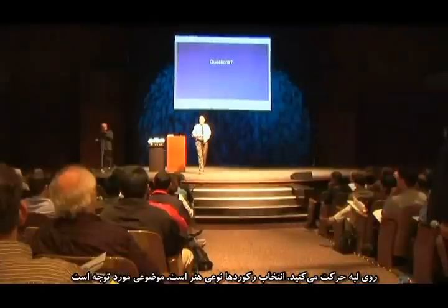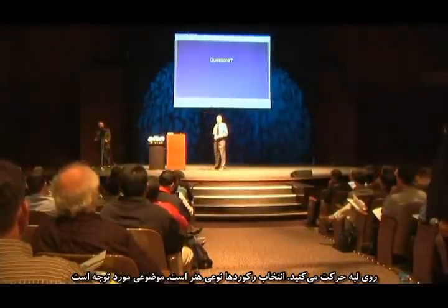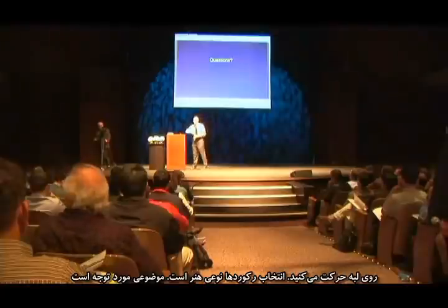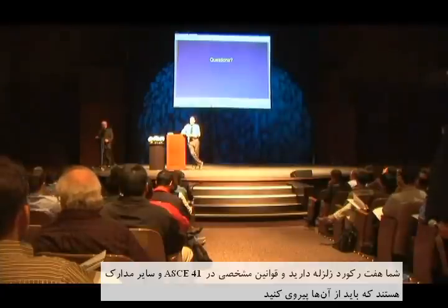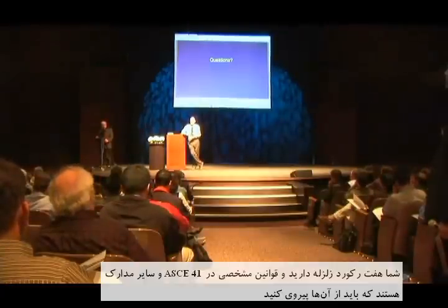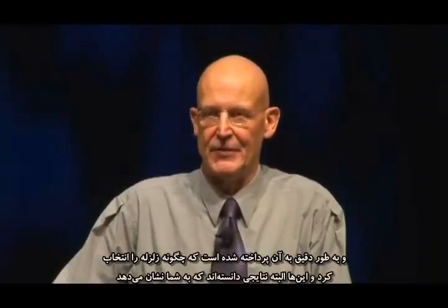Oh, anywhere. You can go online and get them. Choosing the records is a bit of a black art. This is a matter of debate. If you have these 7 records, there are certain rules that ASCE 41 and other documents establish that you should follow. But it is admittedly possible to kind of cherry pick your earthquakes a little bit. This is a matter of intense debate in the academic community about exactly how you pick the earthquakes. And this is something of an unresolved issue.